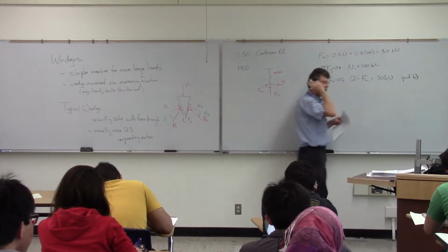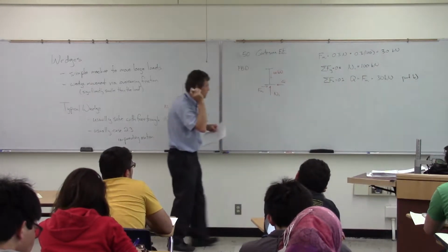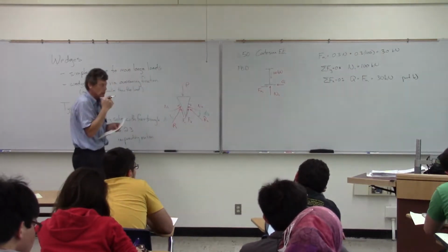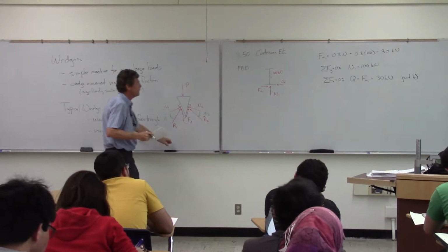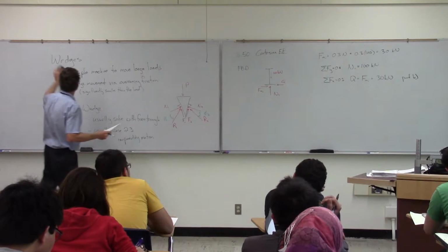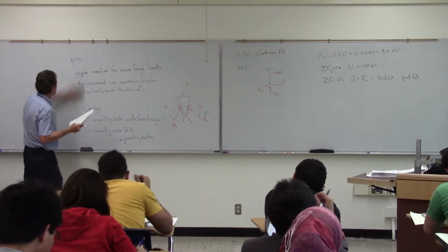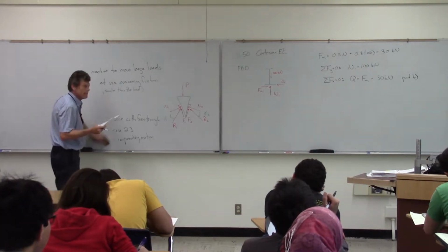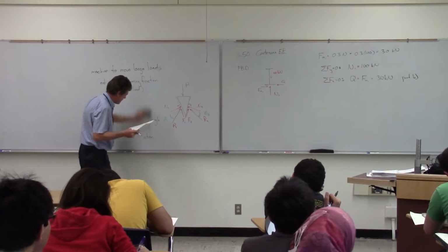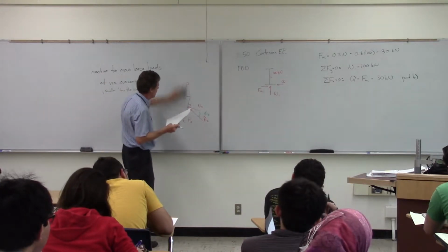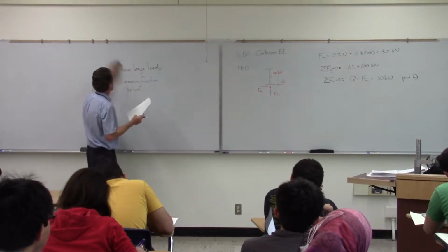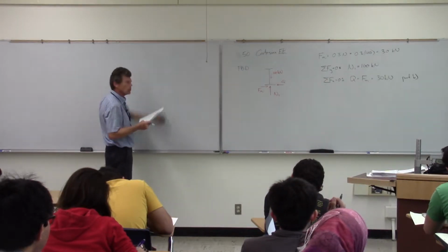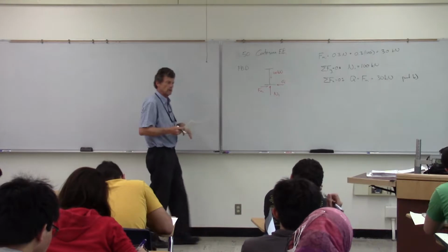Okay, so we already solved part B right off the bat there, because to keep that piece in equilibrium, basically Q has got to be equal to that horizontal force of the friction. Doesn't it not have to equal it, but it has to be less than it? You're talking about max? If it's not going anywhere, if we want it to be stuck there, yes, it has to be less.